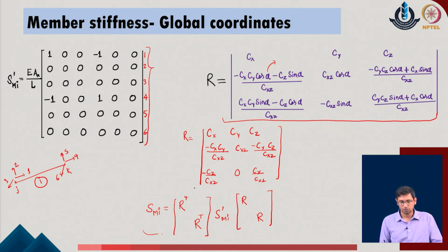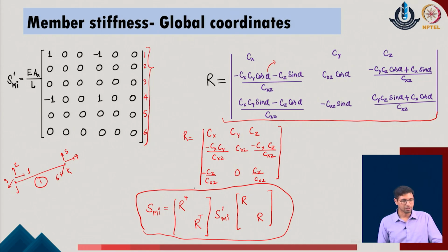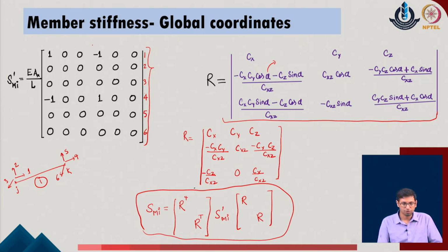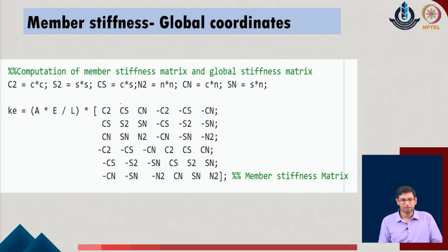So, with this part, once we are able to identify the stiffness matrix for each individual member, we can start assembling them. As a simplistic process, if you cross check the multiplication of this part with the rotation matrix, we will realize that as row number 2, row number 3, row number 5 and row number 6 are 0 for the given system, these expressions do not get introduced in the given problem. We get all the values only in terms of Cx, Cy and Cz of the given problem, and that is what typically is arranged here.